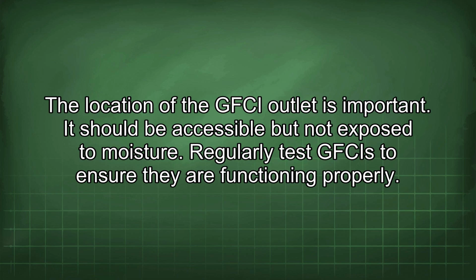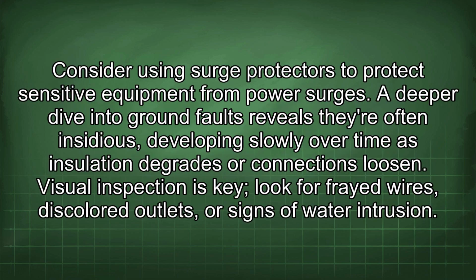It should be accessible but not exposed to moisture. Regularly test GFCIs to ensure they are functioning properly. Consider using surge protectors to protect sensitive equipment from power surges.